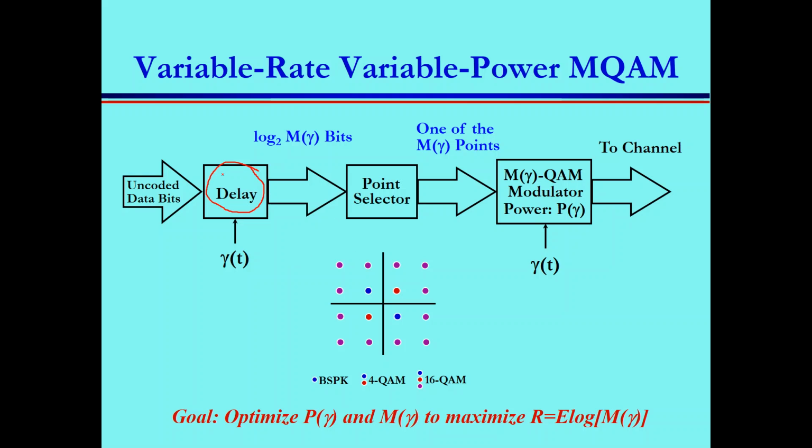So the same, the transmitter here waits for the receiver to send feedback about his signal to noise ratio or his fading situation or the application he's using. And then based on these parameters, for example, channel, application, fading, you feed them into a number. The transmitter has this mapping table. If he receives this number from the receiver, this means use modulation number 1. If he receives number 2, use modulation number 3, 4. So the receiver does some processing and decides which mode suits him the best.